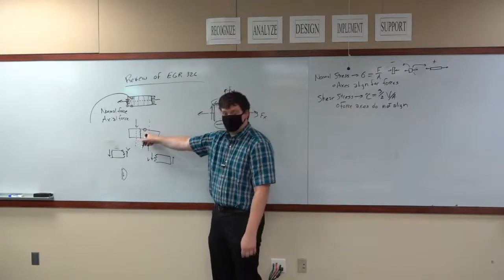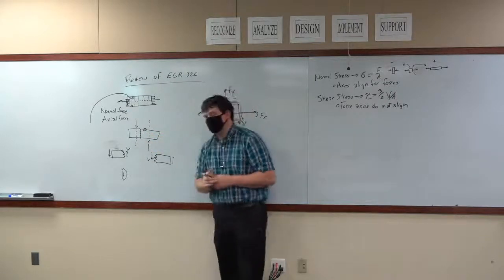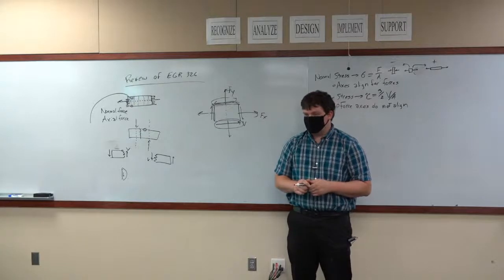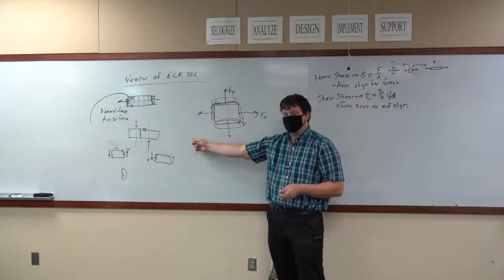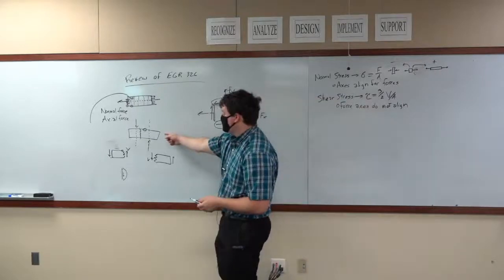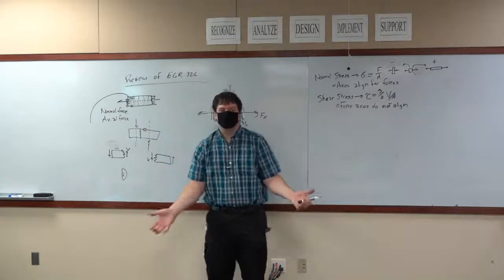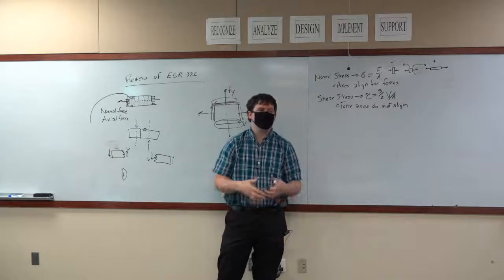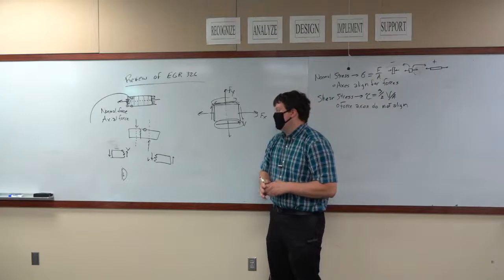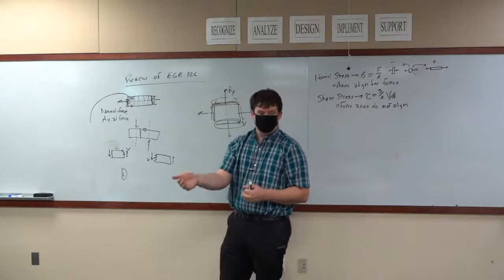shear stress at this location at the very top of the beam, where you're going to see your maximum bending load. If you assume that 3/2 V over A occurs at that same location, then if somebody says, is it going to fail, you've done your math, you will always be able to say no with confidence. Because you made the assumption that shear stress is maximum here when it's not, you over expected a stress at that location, you over provided the calculations, and now you can confidently say, I know the assumptions I made are too conservative.